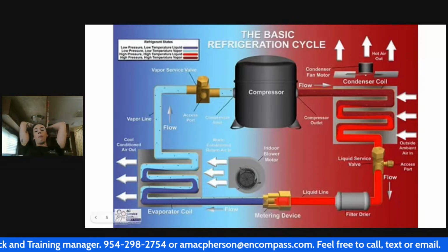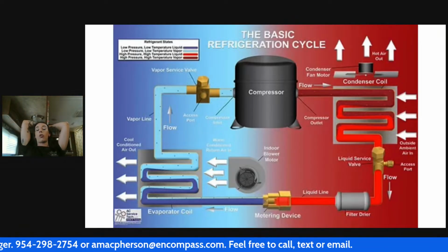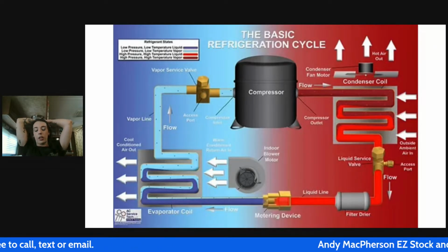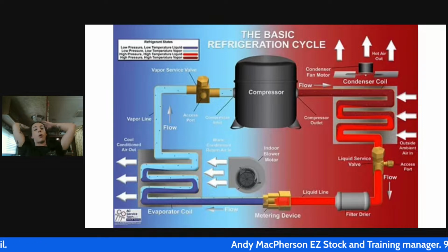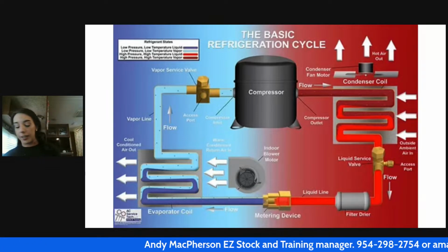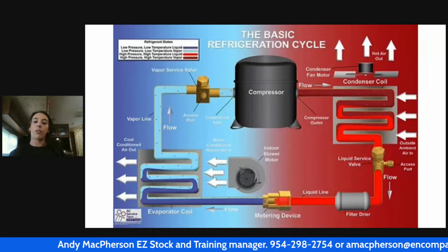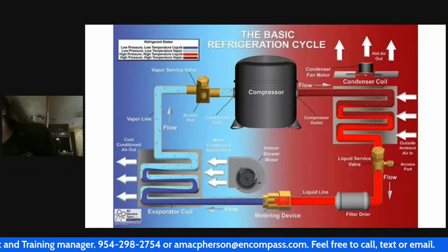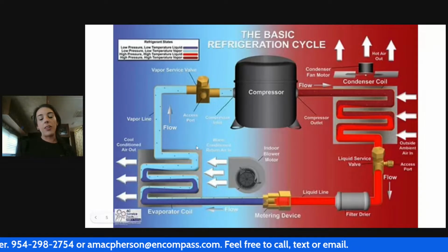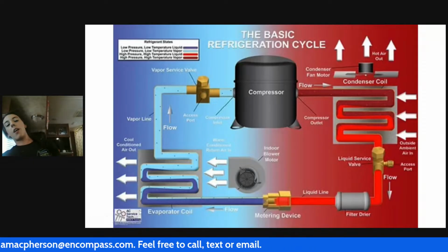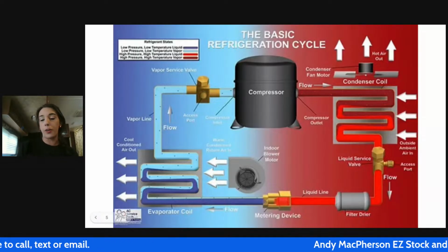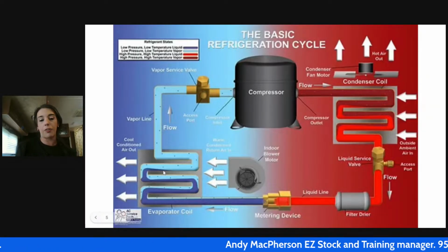It's so important that we not only have a great refrigeration cycle happening and that we have a proper charge to max out that great refrigeration cycle, but the airflow is so, so, so important. And unfortunately, as technicians, it tends to be the thing we forget the most. So if we see things on our gauges, like our evaporator temperature, and this one that is on the page, honestly, would probably be right around 40 degrees, which is our perfect AC evaporator temperature for the moment.